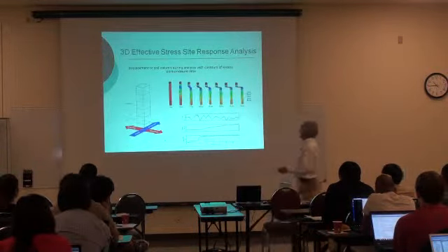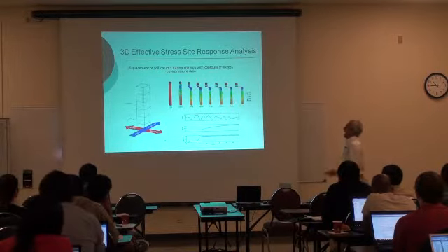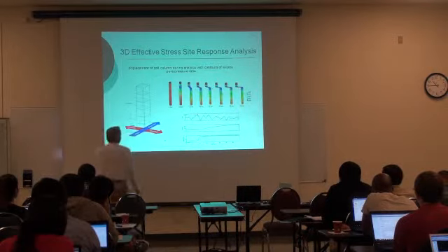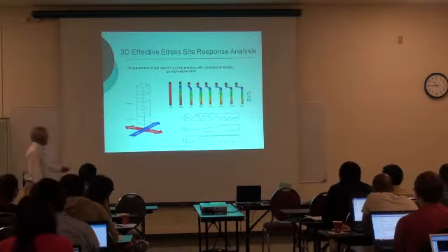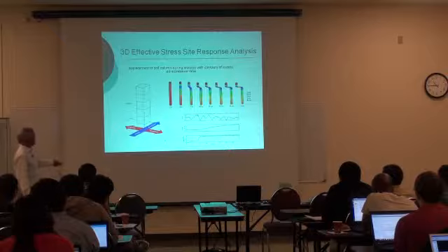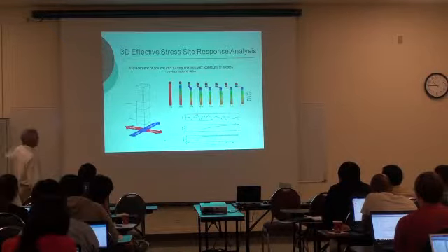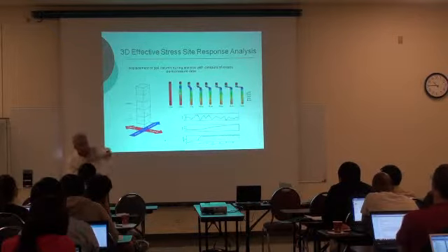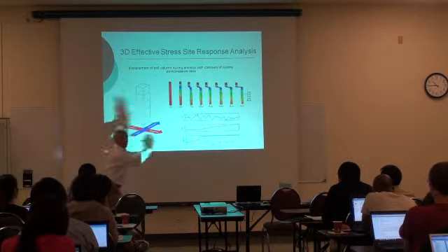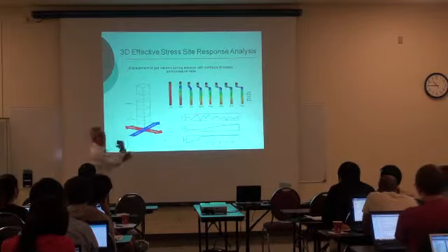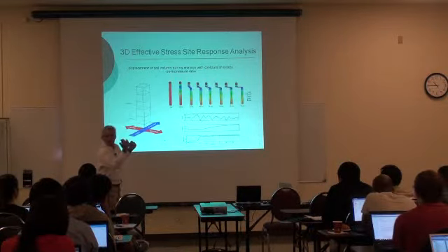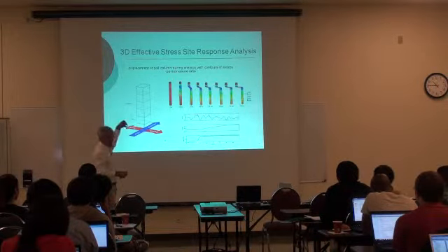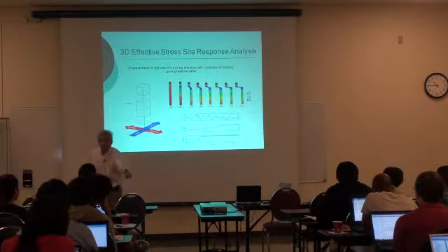This can be also done using 3D analysis. Now, instead of using the 2-dimensional quad, what you use is the brick element. And you can do some funny things. For example, you can shake in that direction, but you can impose a slope in the other direction. So it's like having a slope that is going down, but you shake it in this direction. So you say, well, nothing will happen in the perpendicular direction. Well, if the soil liquefies, it loses completely the strength, and boom, it's going to go down.